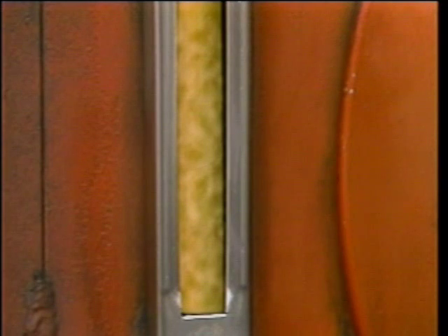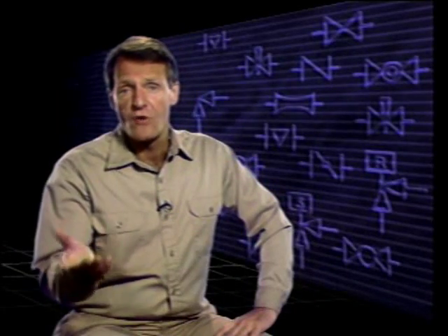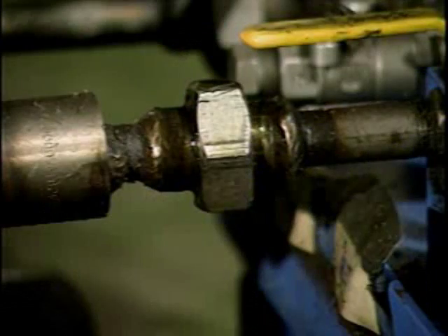Common sources of water leaks into hydraulic systems are heat exchangers. Many hydraulic systems have some type of heating system on the hydraulic reservoir to keep the fluid warm so it'll flow smoothly. In many cases, steam is used to heat the fluid. If a steam leak develops in a heater, the fluid will become contaminated with water. Heat exchangers that are used to cool hydraulic fluid can also develop leaks that can cause the cooling water to leak into the hydraulic fluid and contaminate it.